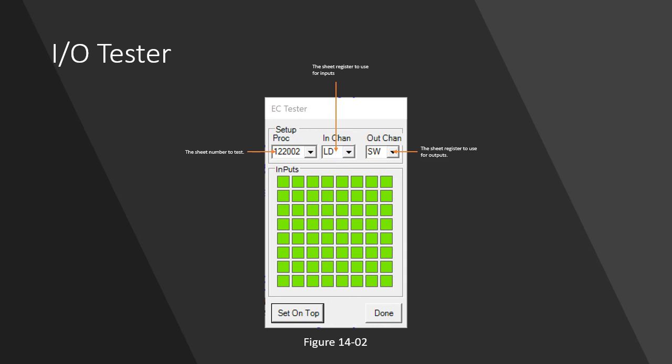And so we typically set that to your switch row so that the logic for your pulse or your toggle or your straight happens and goes out to the field. If you wanted to bypass that there again and just put directly out to the A out, then you could change that to AO and it would put directly out to the output for 500 milliseconds, which is the output time for this when you click the LEDs here.